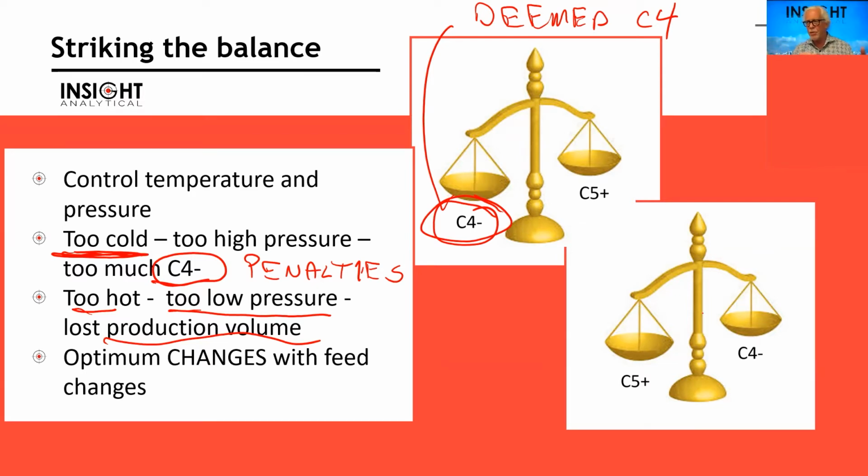When we have a temperature measuring device in a big vessel like a stabilizer, if it's hot outside, there's different heat losses towards the wall and through the thermal well that the RTD is in. And so even things like ambient conditions changing can change what your set point, as measured by those transmitters, should be. So it becomes a difficult kind of issue.